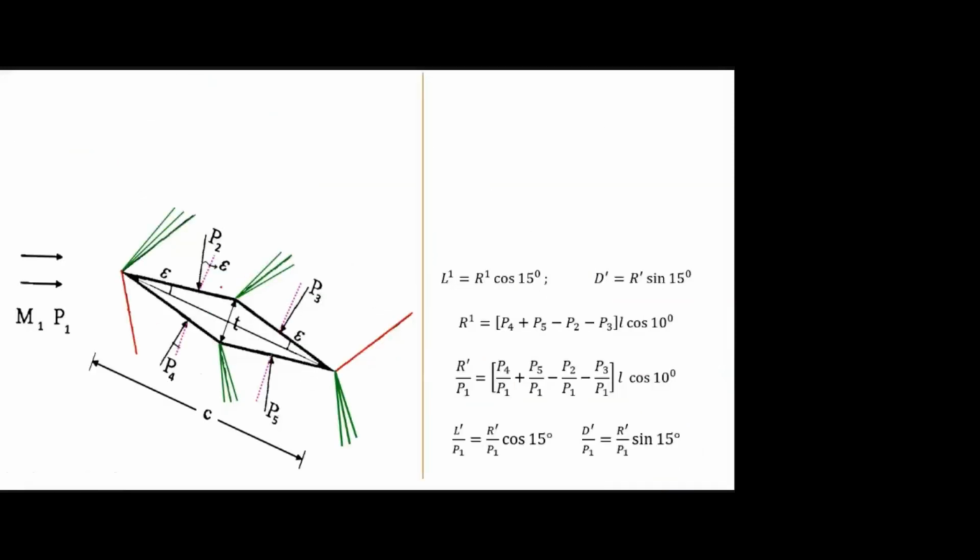So here, you know how pressure will act. This we discussed in the last class itself: it will be perpendicular to the wall. And in this direction, the resultant force will act. That only will resolve into lift and drag, and this will be alpha. Is that clear? So here also we first find the resultant force in terms of pressure. From there we can find lift and drag. And already I explained how to resolve the pressure components.